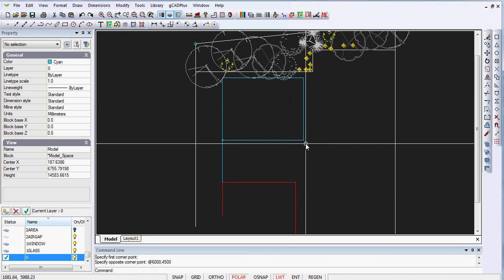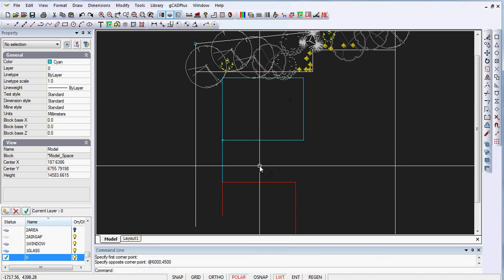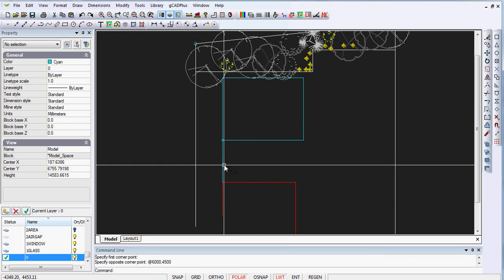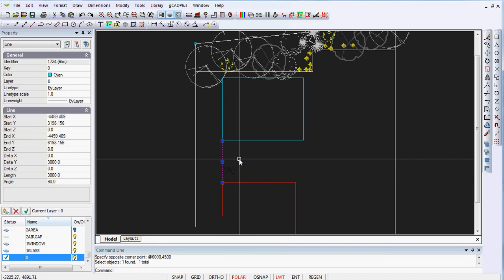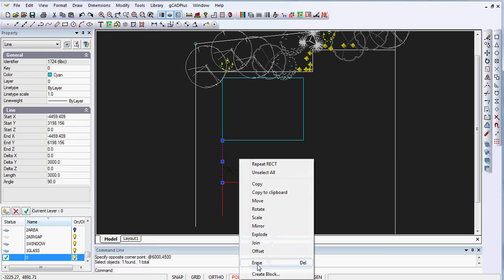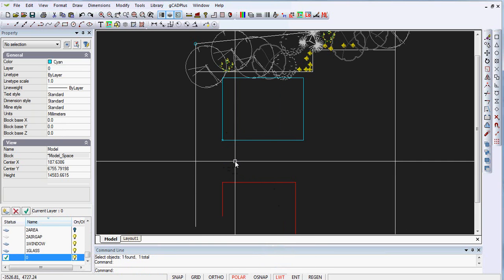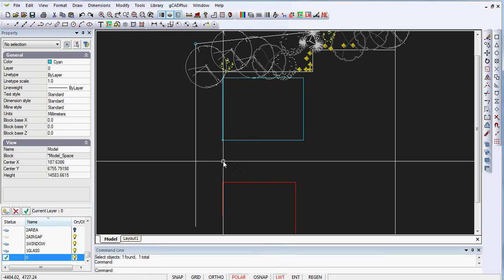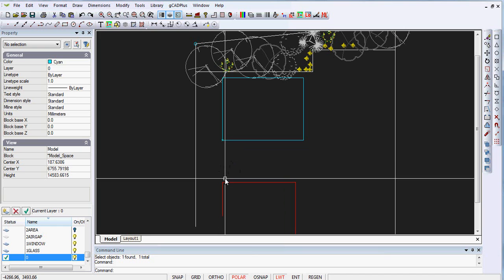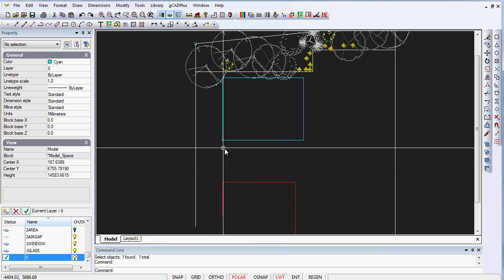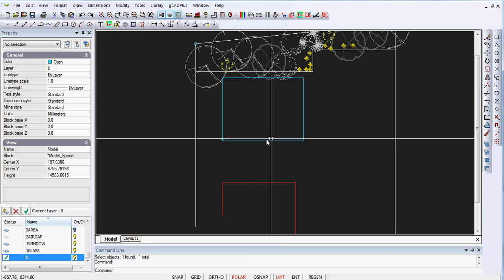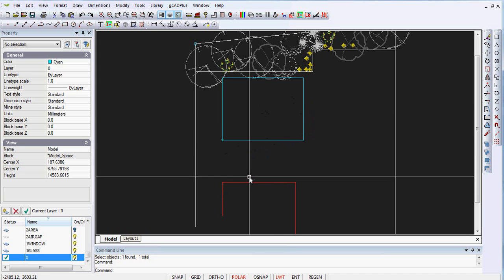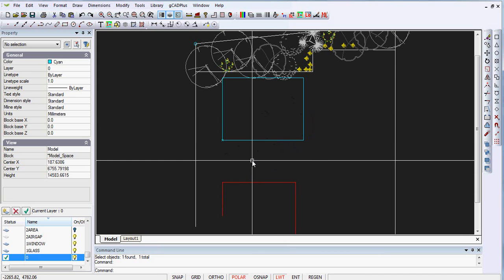So in goes the correctly and accurately placed rectangle representing what will be the vegetable plot, and then we can select that line and erase it. So we actually haven't used the Cartesian coordinates. We picked up the location just by snapping to a line, and then we've used our relative coordinate system to accurately plot that rectangle in place.